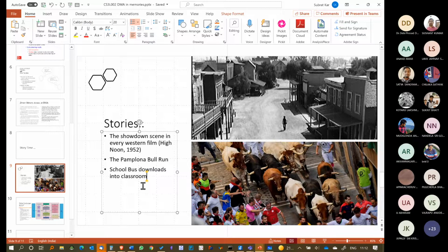Form a queue, which means use a temporary swap space in which you keep those 5 children. Because making children come down from the bus is like a read operation from a memory device. Making children go into the bus is like a write operation into a memory device. To switch from a read to a write takes time. So if you say, okay, everybody who's getting down, please stop while I go in and get my water bottle, then it's going to take more time. So by forming a separate queue for these 5 children who want to go back into the bus, he incurs only one read to write swap time payment.